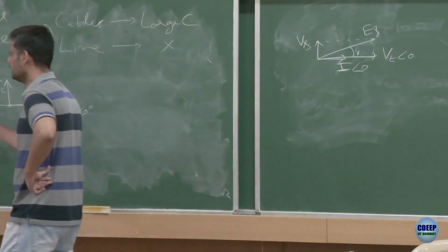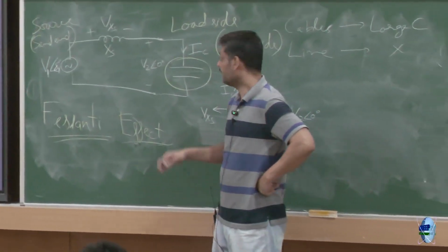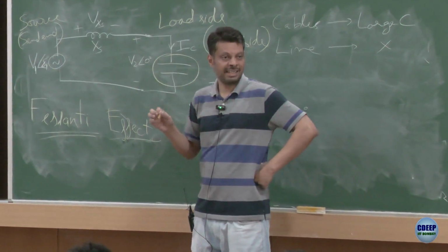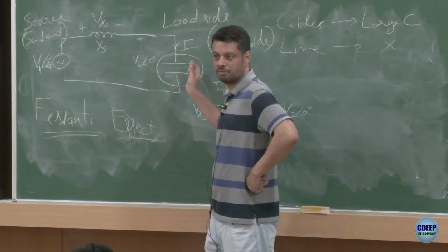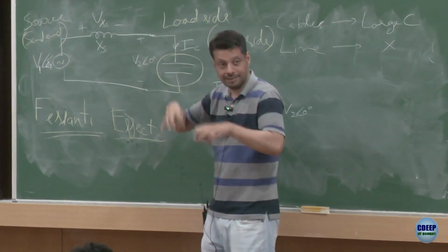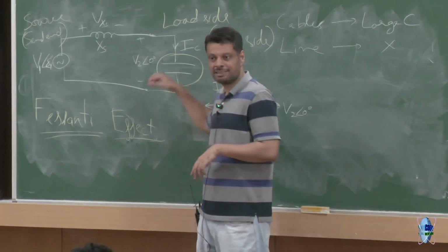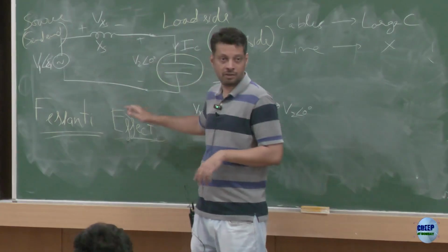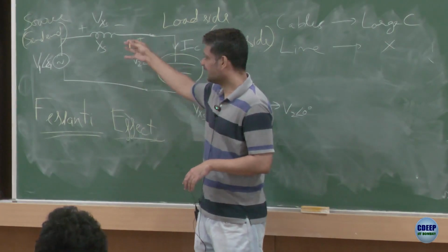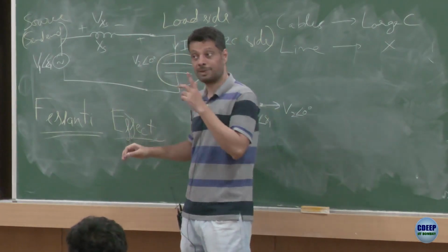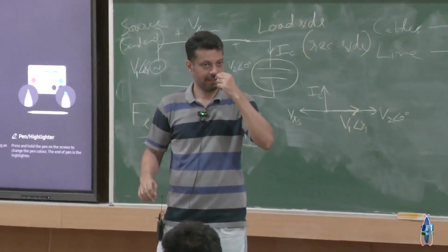Now there are two things here. One is, of course, that the load voltage is more, right? That is one problem. The other problem is, even if you don't have any load connected whatsoever, your line is loaded with some current because of this capacitor. If you don't have this capacitor, the current will be 0, right? Because you have a capacitor, your line is loaded, and this is eating up some of the capacity of the line. In fact, if you remember, that is the reason we said lagging power factor is bad in the previous course in the beginning.